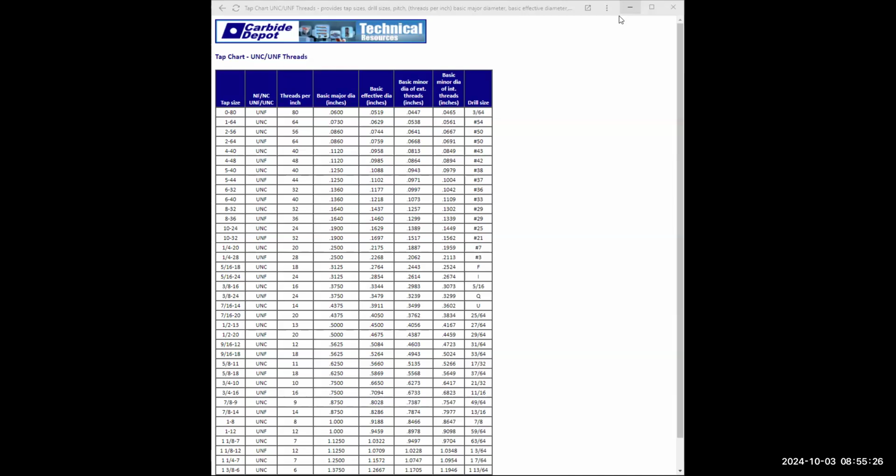So I'm going to click on this, come down, enter. All right. Mr. Morris, why are you drawing those lines out there like that? Well, what I want you to do is click on this line right here. You'll see these 3 little grips that come up. Click on this grip and stretch it all the way across to about right here. Enter. I'll do it again. Click on the line. There's 3 little grips. Click on this grip. Drag it all the way over to about right here. Click. Enter.